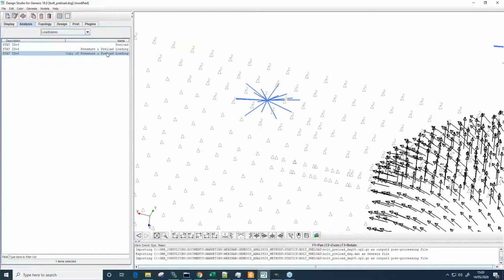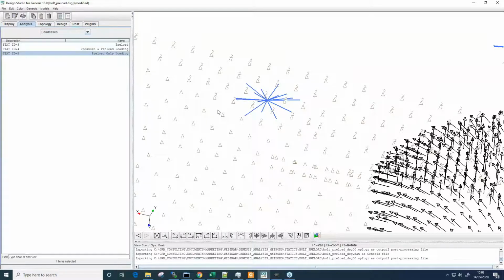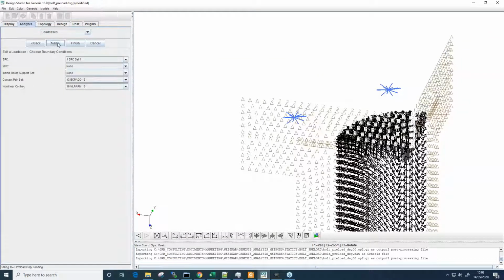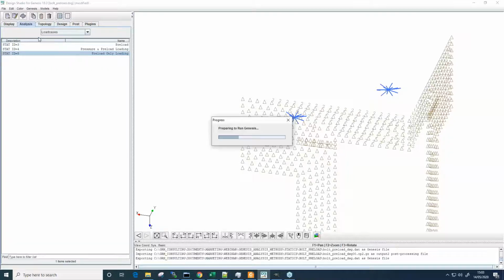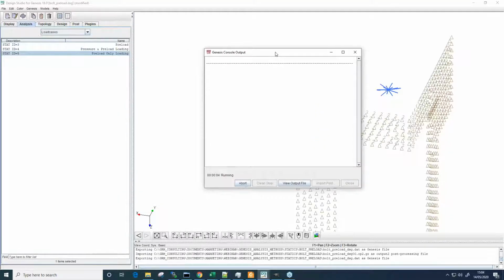This topic is covered properly. So if I do preload only, as mentioned at the start of this preload discussion, the load case of a preload application is applying the force to the bolt. So we know that the tensile force is 5 kilonewtons. It's load driven. What we want to do is trust that's the case, and I want to prove that out here with this solve. So in this preload only case I'm not going to apply any other external force, but I'm going to reference the bolt preload case. So it's going to just simply torque down those bolts as a solve. So we'll pursue this last one.